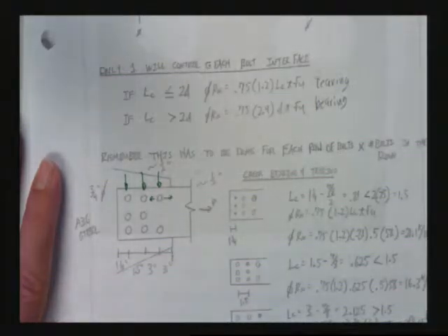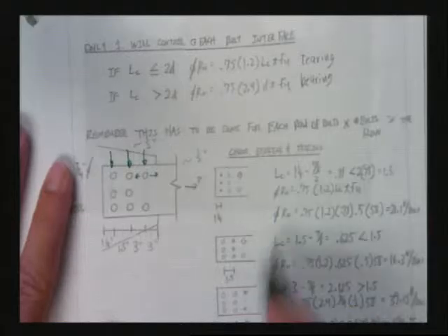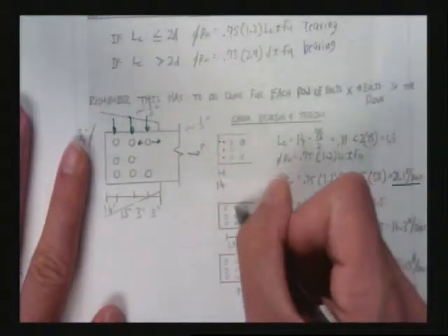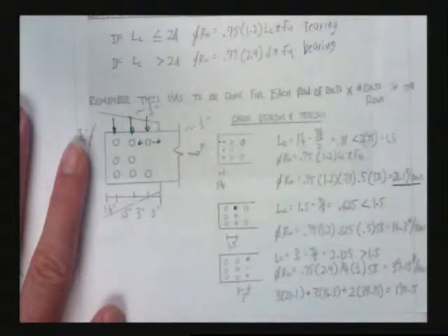Okay, so I've done that here. I've done a calculation for one bolt, and then in the bottom I'm going to multiply by 3. I do a calculation to figure out what the tearing or bearing capacity would be for one bolt in that row. I do another calculation for what it would be for one bolt in that row.